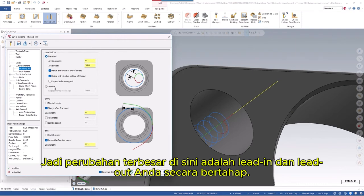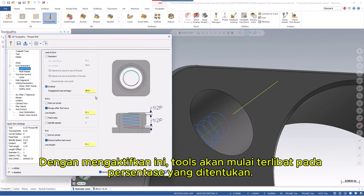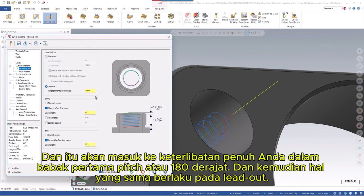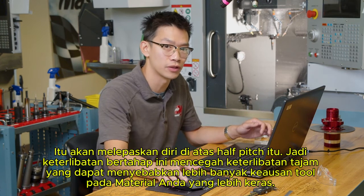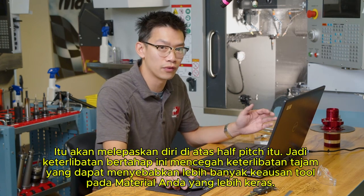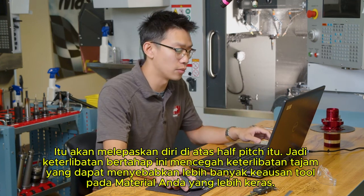So the biggest change here is your gradual lead in and lead out. With this turned on, the tool will start engaging at the percentage specified, and it will go to your full engagement within the first half pitch or 180 degrees. And then the same thing applies on the lead out. It will disengage over that half pitch. So this gradual engagement prevents that sharp engagement that can lead to more tool wear on your harder materials.